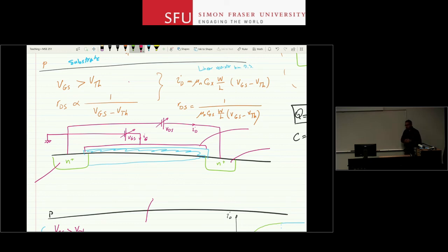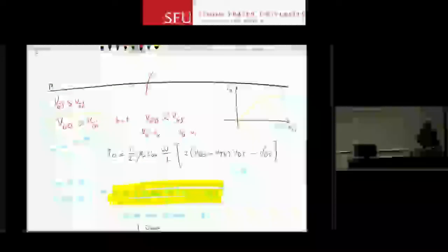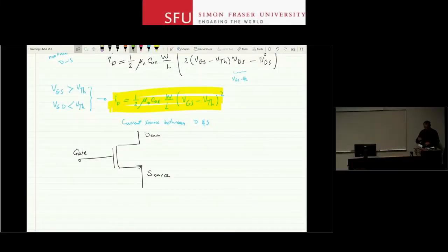You can switch, right? But for a discrete MOSFET, because of that internal connection where they connect the source to the body, it's not symmetric anymore. All of a sudden, the source behaves differently from the drain terminal, which you didn't expect from the structure, but it's because of the connection.